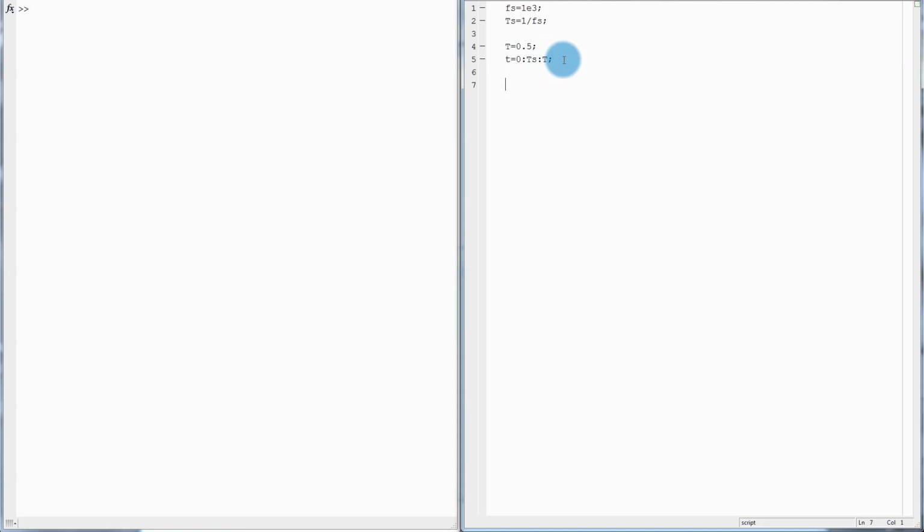Now if I wanted to generate a constant frequency sine wave, I would do it like this. And I would set that my frequency is something like 200 Hz. But I do not want to generate a constant frequency sine wave. I want my frequency to be rising with time. So I need to make my frequency proportional to time. And this will be the constant of proportionality. If you set it like this, your frequency will go from 0 to half the sampling frequency in this time.